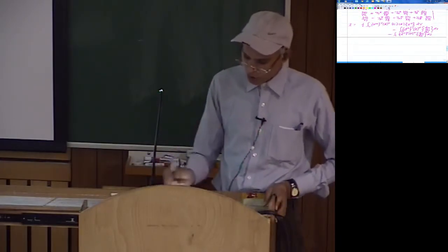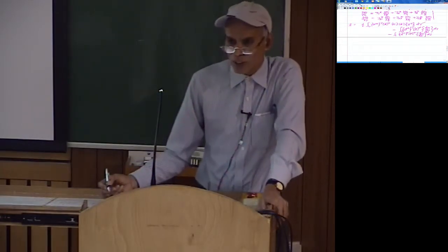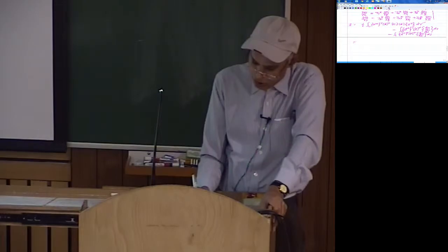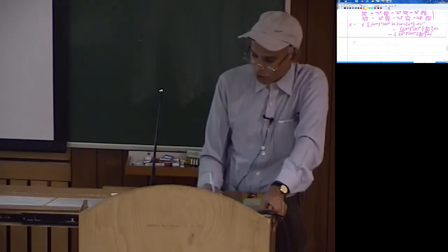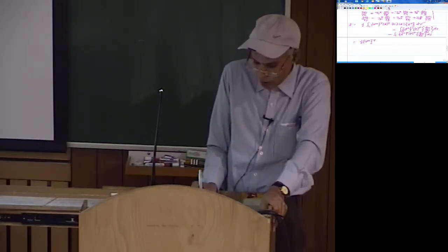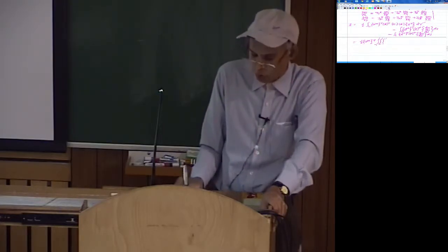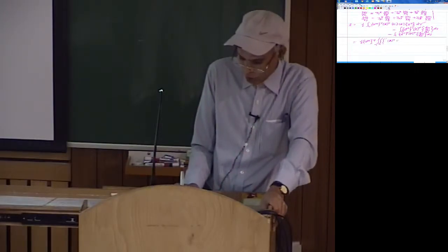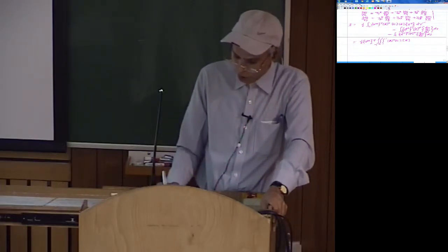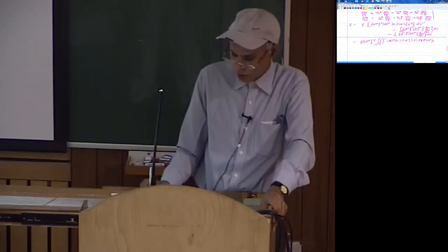And now, since everything here is expressed in terms of xi and eta, we can now write this integral dV in terms of natural coordinates. So what I can actually do is write this, and since this d is independent of xi, eta and zeta, I can take this out of the integration, similarly that side. So I can write this as half and then this as d transpose, then triple integral from -1 to +1, because all the natural coordinates are going from -1 to +1, and then here you have B transpose into C into B, and this I am going to take to the other side. So dV can be written as determinant of J into now d xi, d eta and d zeta.